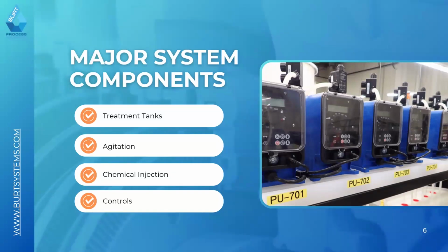The treatment tanks vary considerably. I showed you a couple examples there between some large fiberglass and thermoplastic. Those are probably the most common design for pH neutralization systems. But what's really critical, and this goes for both pH treatment as well as if you're going to look at something like a chemical EDS system, is that you need to have a proper rate of mixing in your system.